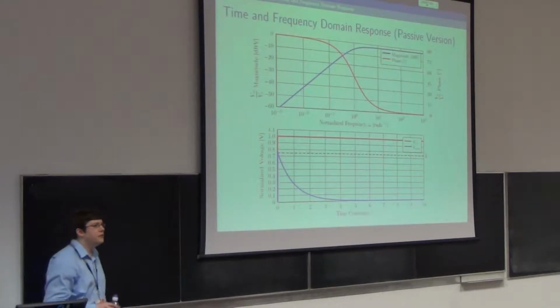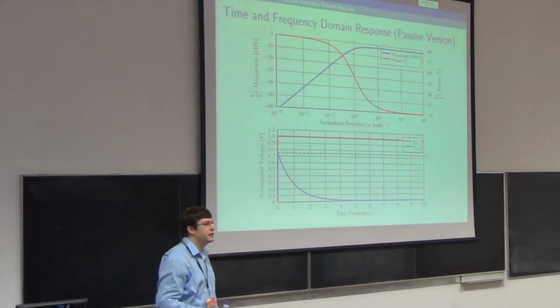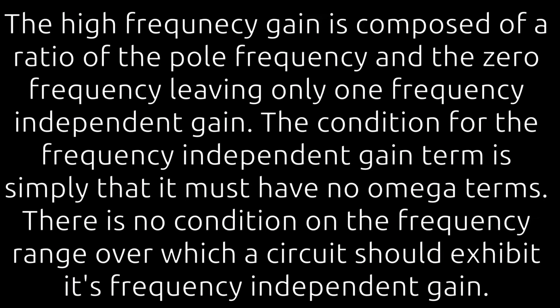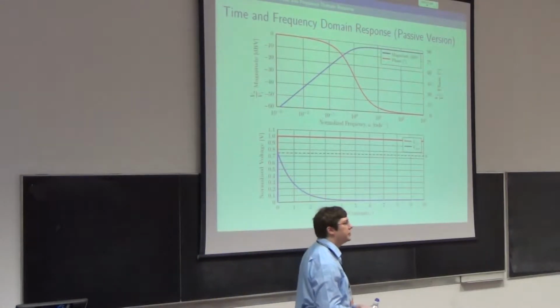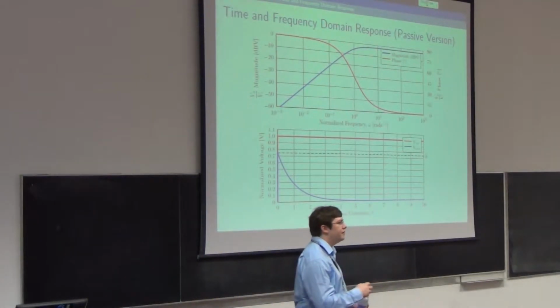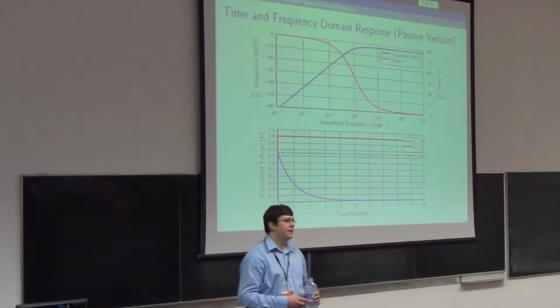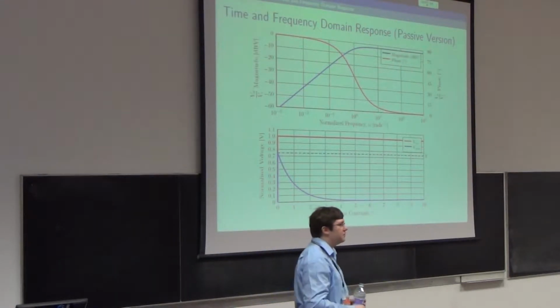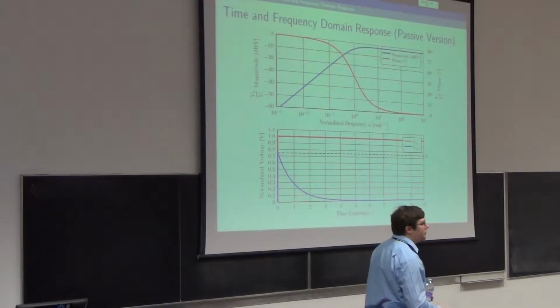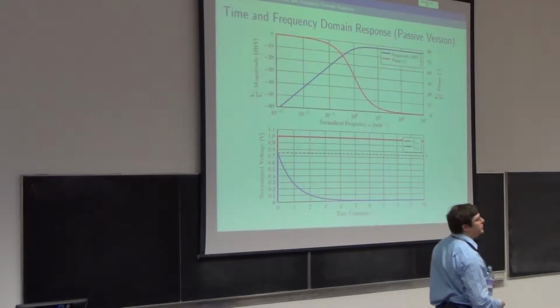It will have a high frequency gain and a low frequency gain. So it will have two Ks, if you like. And it will not really have two time constants, because you can't really count your zeros as a time constant, because only poles generate time constants.